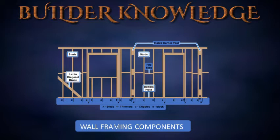Then we have the corner posts. They are constructed wherever a wall ties into another wall. Outside corners are at the ends of a wall. Inside corners are where a partition ties into a wall at a point between the ends of the wall. There are three typical designs. 1. Outside corner construction using only 3 studs. 2. Outside corner construction using 2 studs with short blocks between them at the center and ends. 3. Inside corner construction using a block laid flat. A full-length stud can be used instead of a block.